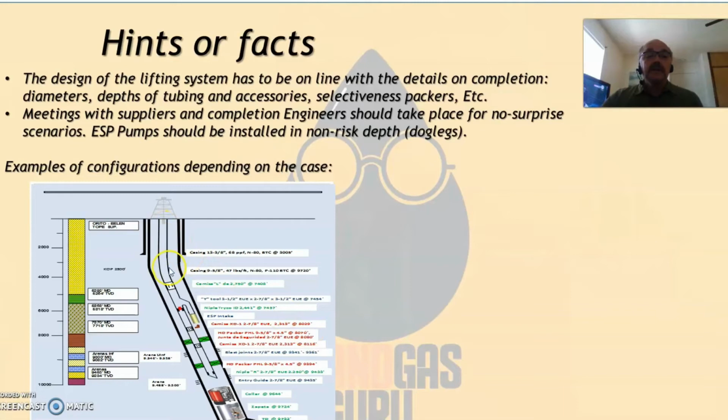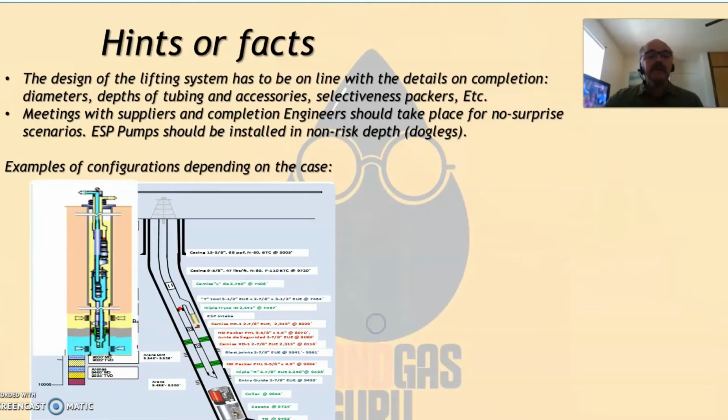But that's an option, a monobore. We can also produce with the ESP pump. We can produce commingled, and because we have a wide tool, we can run a PLT to see the production of each one of the sands, and we can report that to the ministry, so we are legal, and tell them how much each one is producing.